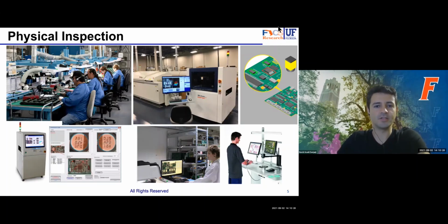We have seen the rise of use of lasers, optical interferometers, and a lot of other modalities that are helping with identifying the components on a board, and also to some degree going into the third level, doing volume analysis with X-ray, terahertz, acoustic, and so on to be able to see these defects either unintentionally there or intentionally there. We have to make sure that we can extract everything abnormal.